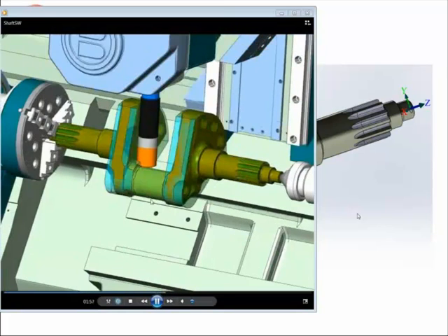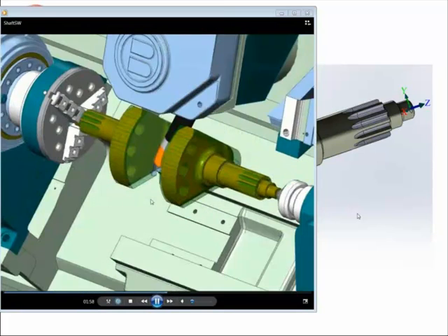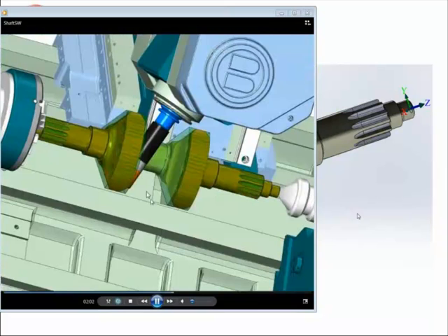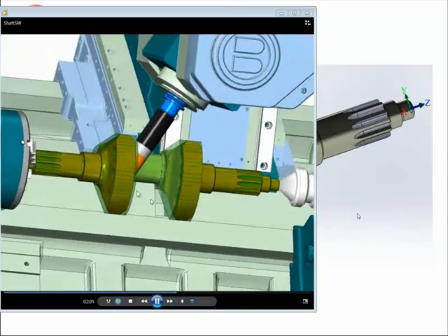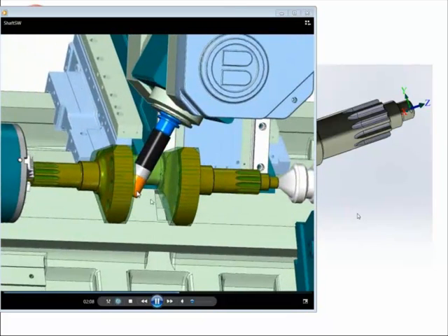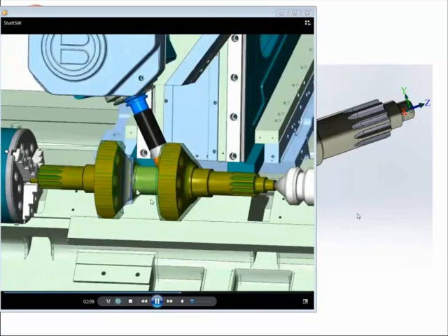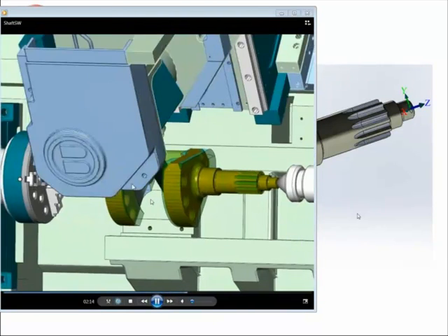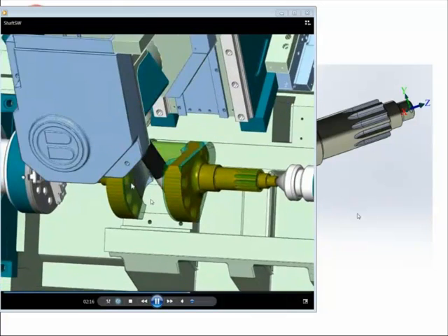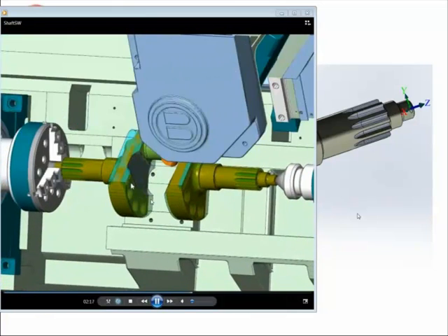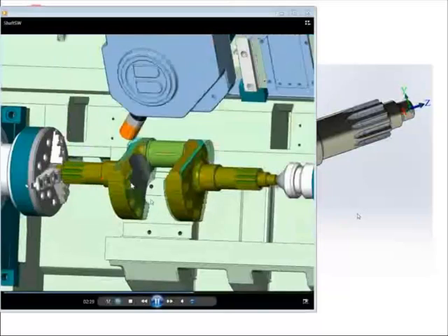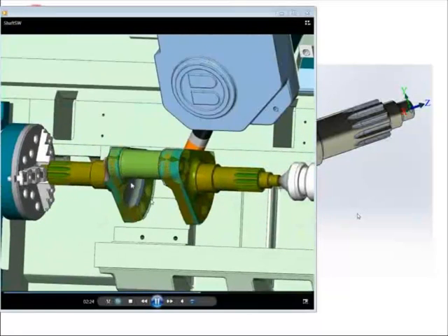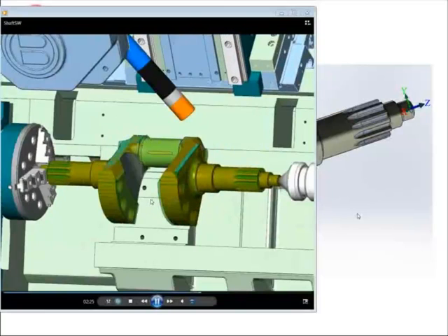And this file is really showing all the capabilities. Collisions are funny here. They are not funny on the machine. The whole idea is that you want to catch them here and correct them before you put it on the machine. And you can use this tool to really double check everything and make sure that you have an efficient toolpath, not just error-free, but efficient toolpath also.